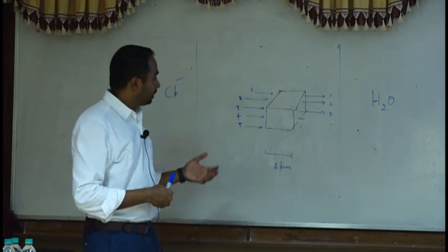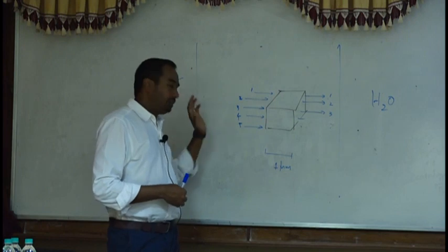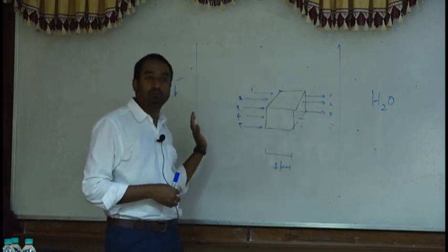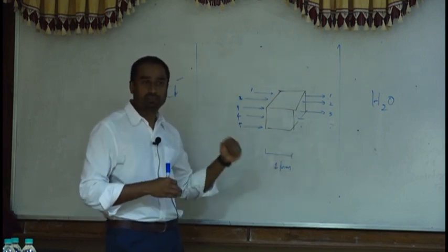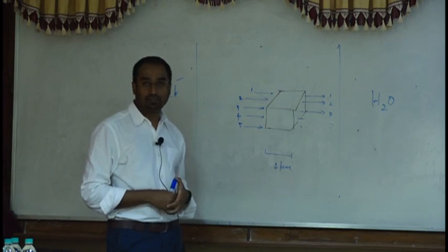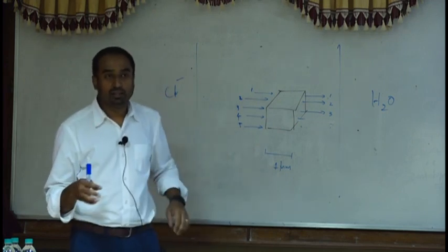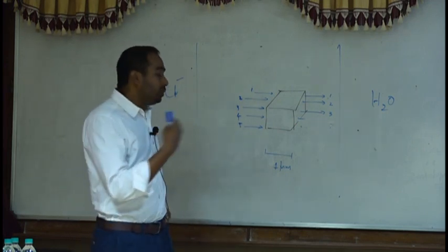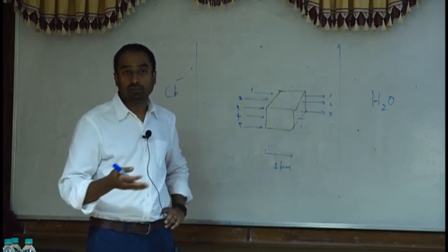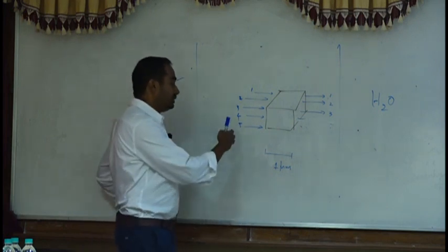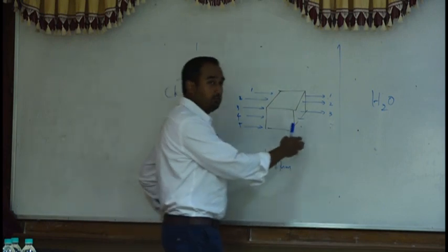Okay. Do you think this system will happen forever, or does it have a shelf life? After a certain time, the reaction potential will dry, which means the amount of chlorides it can hold back will be 0. So at that stage, if 5 comes in, there will be 5 going out.